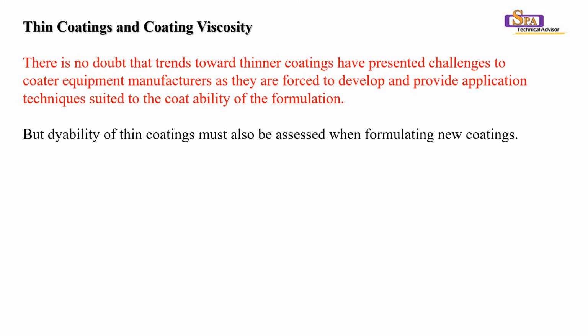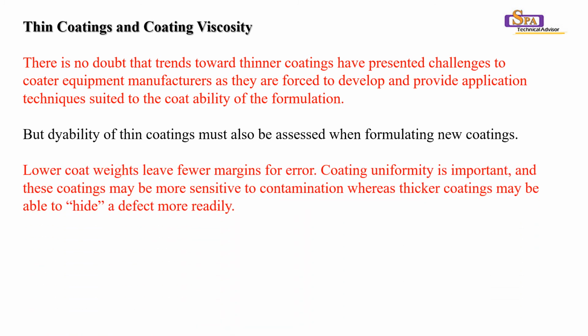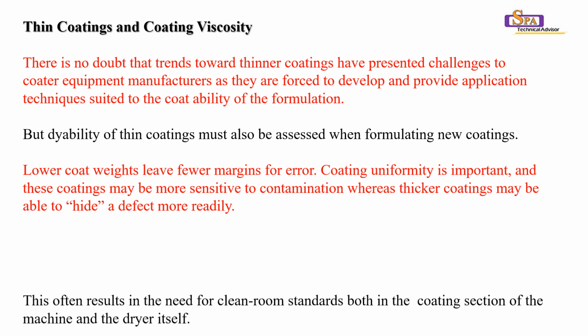But dryability of thin coatings must also be assessed when formulating new coatings. Lower coating weights leave fewer margins for error. Coating uniformity is important, and then the coating may be more sensitive to contamination, whereas thicker coatings may be able to hide a defect more readily.